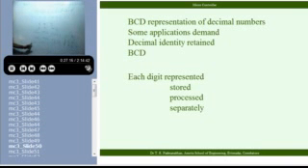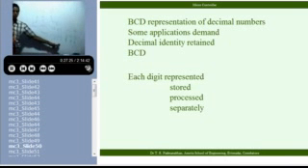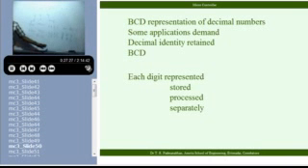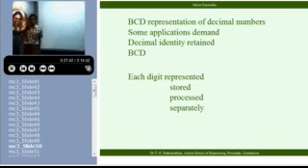One confusion is, I got here a 5-bit number, which I don't allow. Another is, I got a representation which is not available. This 1010, in the corresponding hex form, is 8 plus 2, 10. But you don't permit that. You only permit representation from 0000 up to 1001, only up to 9. Beyond that, it is not available.